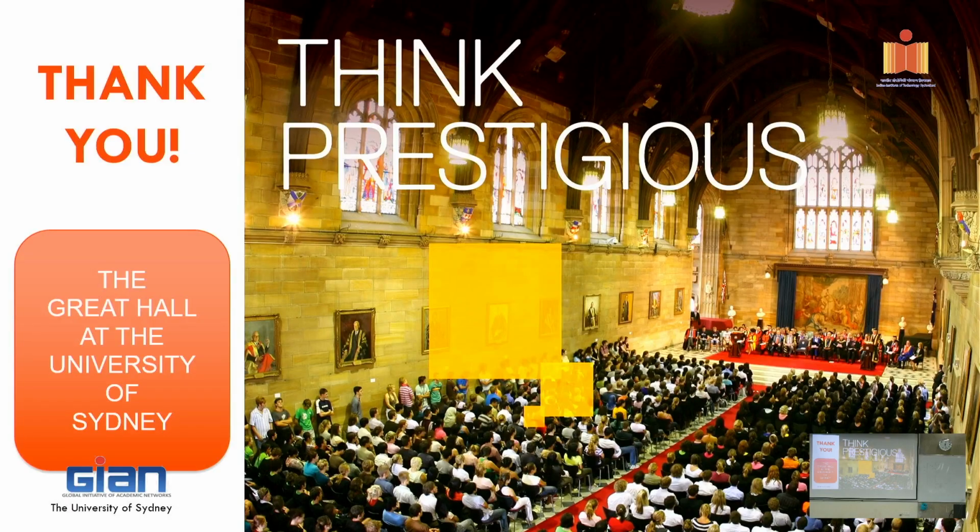Right. Okay, so again, you raise a very interesting question as well. For member capacity, we're using a very simple function because it's subject to a constant stress distribution, right? Normal stress or shear stress or whatever is constant along the member. But with localized loading, when you have something at the end and you put a very localized load on the member, then the buckling is a lot more complicated, right?